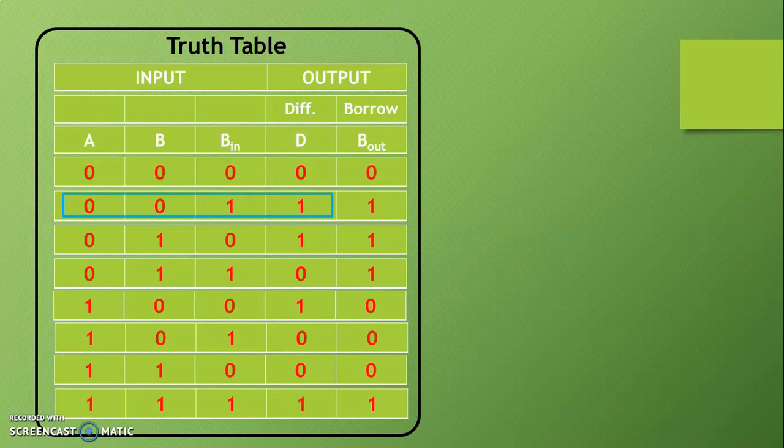So first we check. So condition 0, 0, 1, we are getting difference D high. 0, 1, 0, again we are getting high output in difference. 1, 0, 0 and 1, 1, 1. For the 4 different input combination, that is 1, 2, 4 and 7, we are getting a high output in the difference D. This minterms we can use for the K-map.